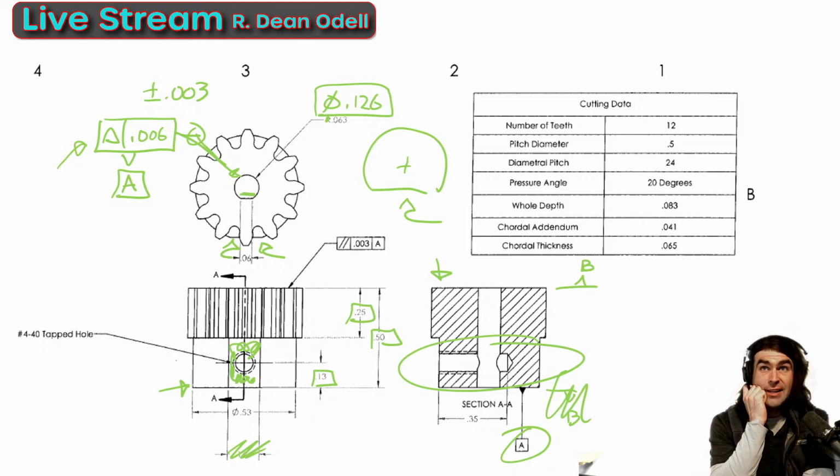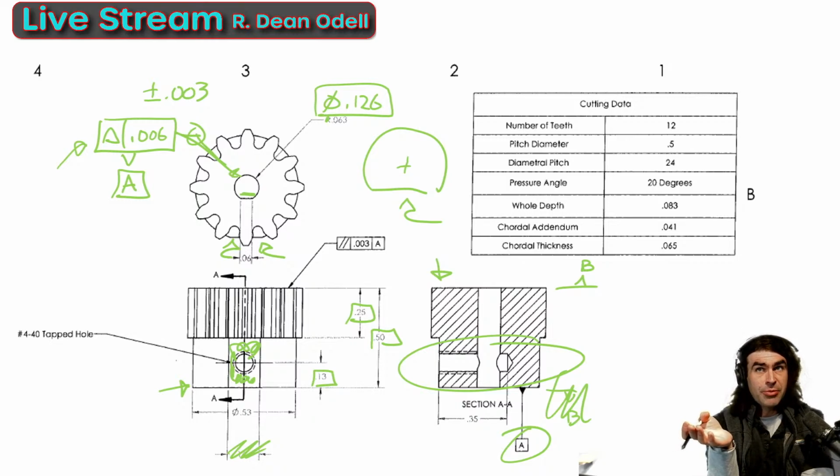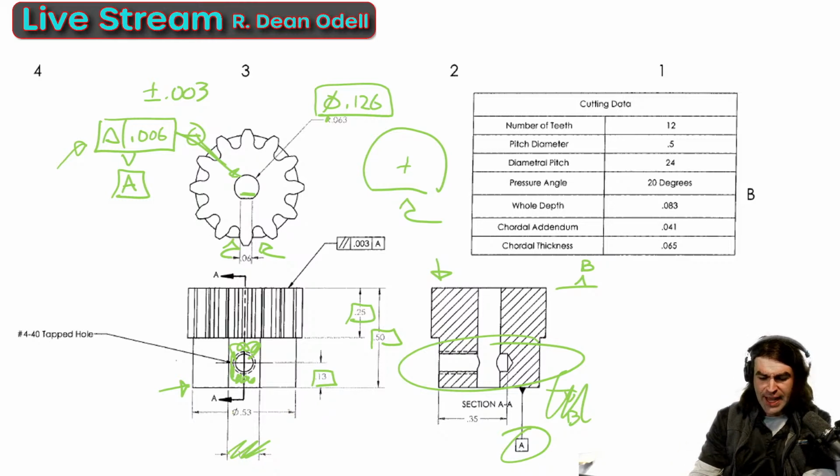They actually got rid of that. So they said, hey, obviously I don't remember the exact wording, but basically you can apply runout to something that has surface interruptions as long as the part that's supposed to be round, the runout applies to that. It doesn't apply to the flats. So that being said, I'd consider applying runout to here.